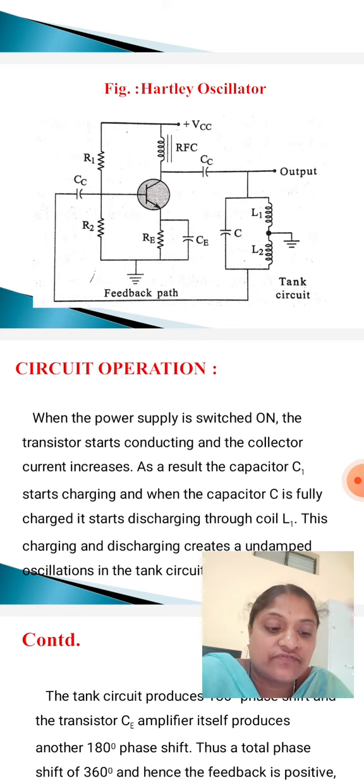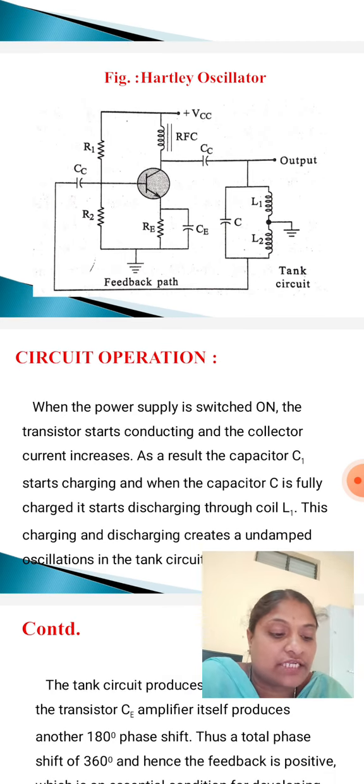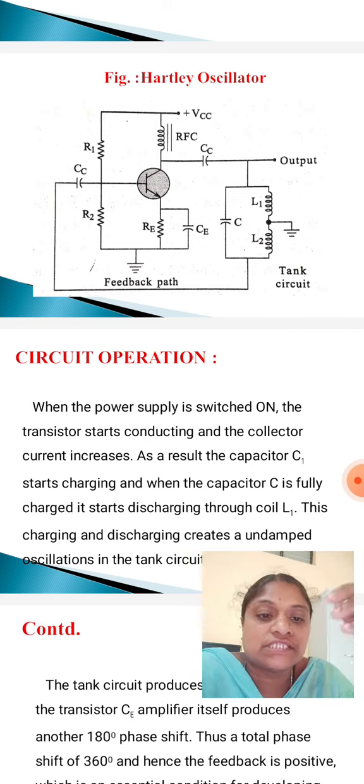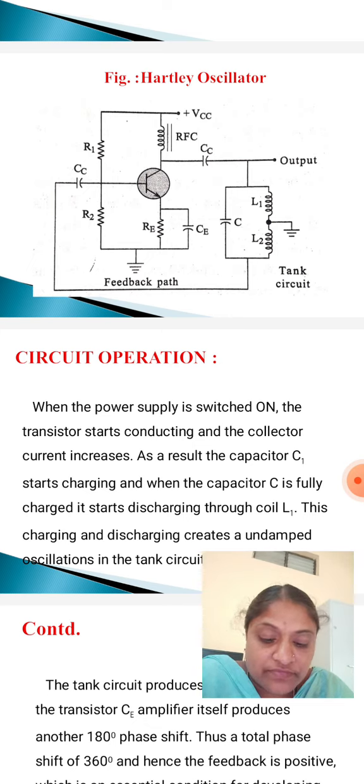What is the purpose of RE? RE provides thermal stability for the transistor. And next CC. CC means input CC and output CC. CC means coupling capacitor.